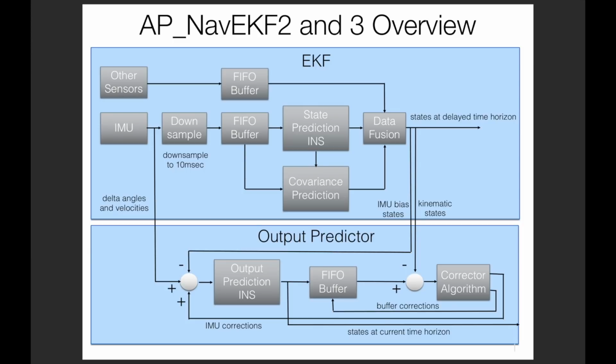We then take that measurement of position that was formed with a large contribution from inertial data, and then we fuse it into our EKF that's doing prediction with inertial data and takes this data and assumes it's an independent observation. And it's not a good way to do it. It runs into problems, particularly if the inertial odometry system starts to go into dead reckoning mode. So now I've got an EKF that's using an inertial odometry system to prevent dead reckoning drift, and the source that's feeding it is dead reckoning. And we really need to get that scale factor into the equations.